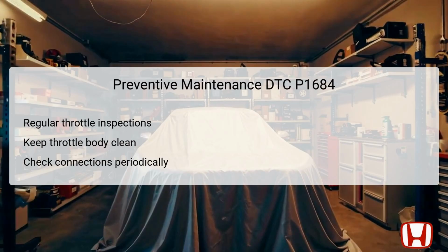Technicians should also periodically check all electrical connections associated with the throttle body and the powertrain control module, PCM, to ensure there are no loose or corroded terminals that may influence overall performance. By implementing these preventive measures, owners can enjoy a well-functioning vehicle and minimize the likelihood of encountering similar issues in